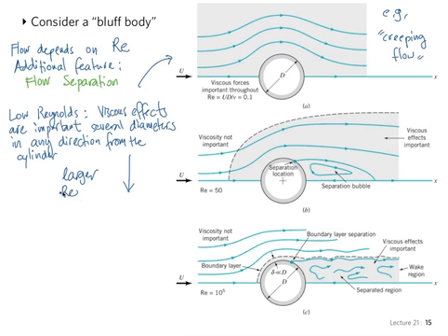So basically, larger Reynolds numbers are associated with thinner boundary layers in the case of a flat plate, and in the case of a bluff body, with the viscous effects being confined to distances closer to the body, except for the case of this separation.